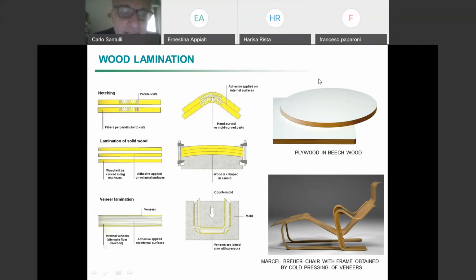As a general consideration, fibers take the tensile load. So if you want the material to withstand also some tensile load, you need to have fibers as long as possible. Okay, and then you have some layers of materials. As you may remember, wood, especially solid wood, is particularly loaded in bending, in flexure. So that's the way in which it is tested usually.